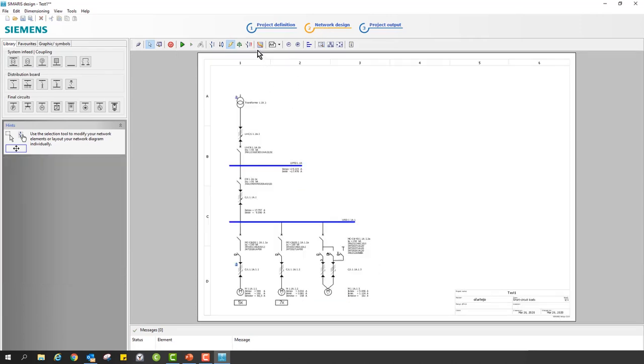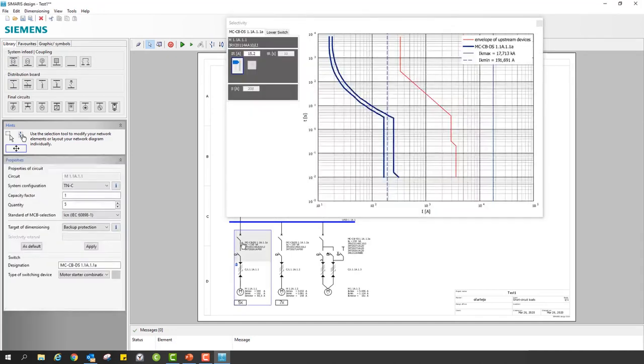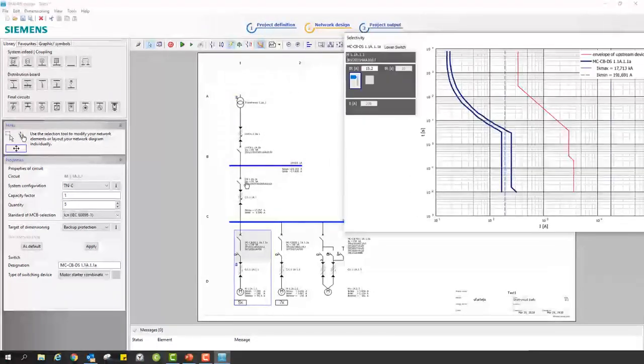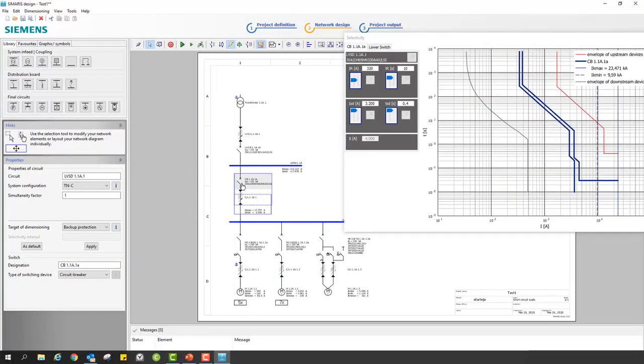If you do this for a different type of contactor or one that is not tested with this MSP, you cannot confirm that this will actually go up to 150 kiloamps like we do in our type tested combinations. It has to be the same reference of contactor. This also has to be placed in the documentation, and once again, it's a way that you can argue with your customers how the design is better for him, of course, when using type tested combinations from Siemens.